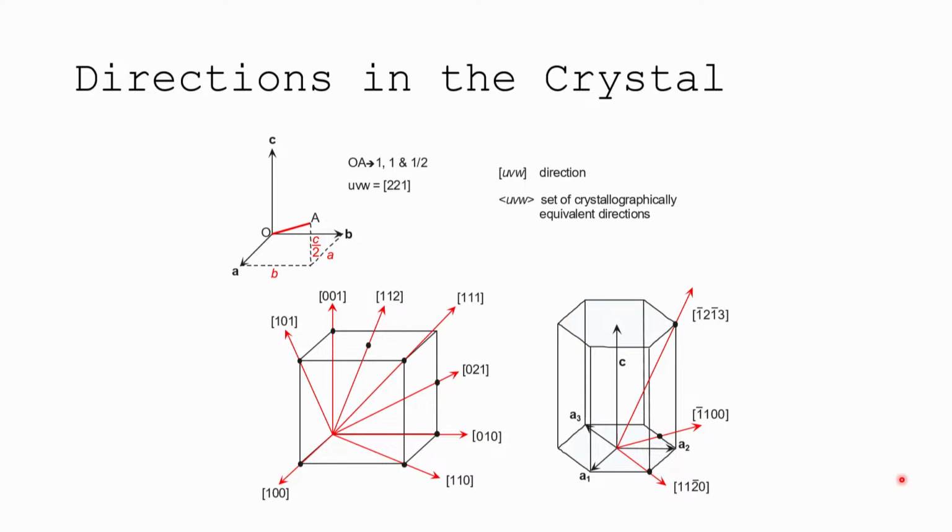All right, so if we go to something that is not defined easily by A, B, and C, and we need to get the angles involved. So this is hexagonal and trigonal crystal symmetry specifically. We go to a redundant fourth index to define that. And so we will have, instead of A, B, C, we have A1, A2, A3 defined in the plane that are aligned with specific directions in that hexagon. And then the C-axis showing the axis along the hexagon, the hexagonal prism, let's say. So then if you move along one of these directions that is aligned with one of the A directions, A1, A2, A3,